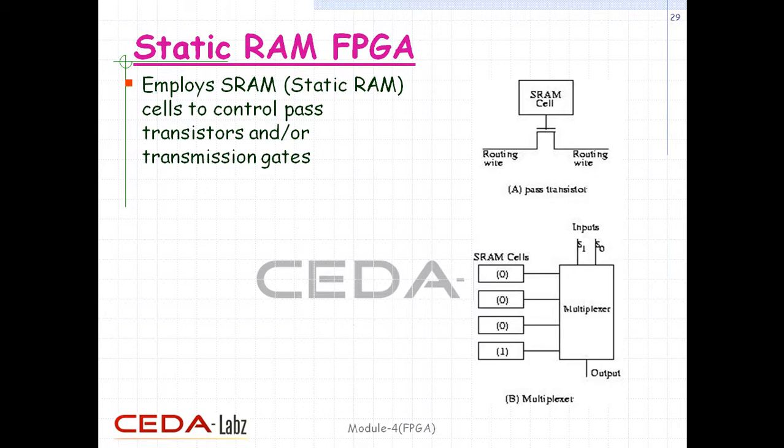Each bit in an SRAM is stored on 4 transistors, M1, M2, M3 and M4, which form 2 cross-coupled inverters, as shown in the figure. This SRAM storage cell has 2 stable states, which are used to store the states 0 and 1. In the diagram there are 2 extra transistors, M5 and M6, which are used to control the read and write operation. In addition to 6T SRAM, 4T SRAM is also popular.